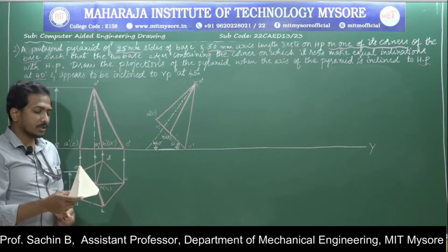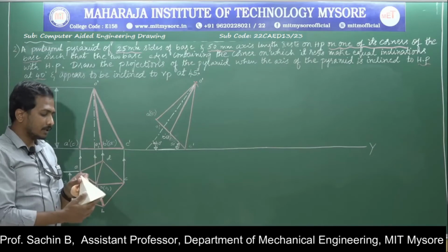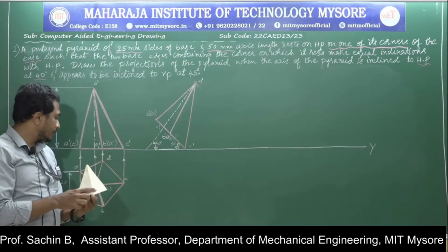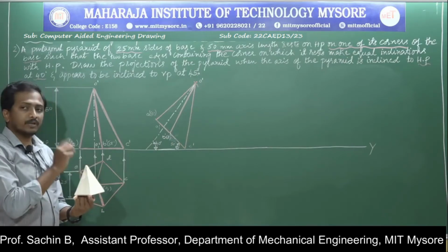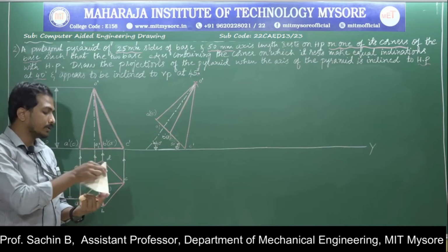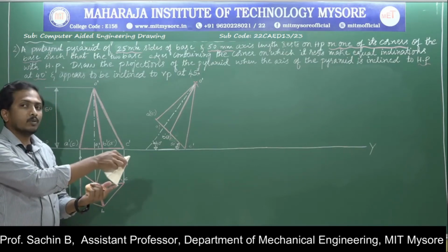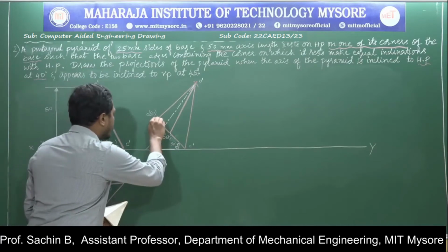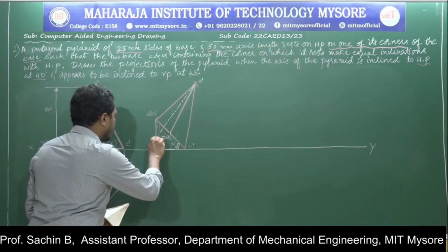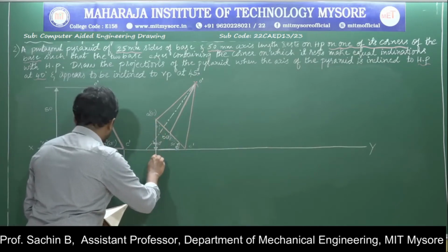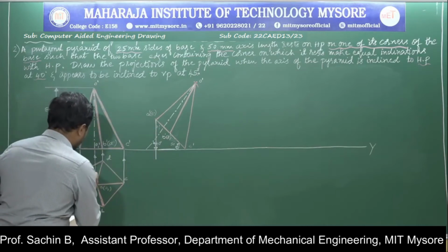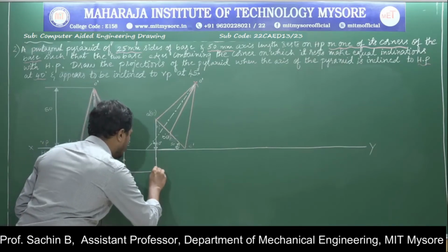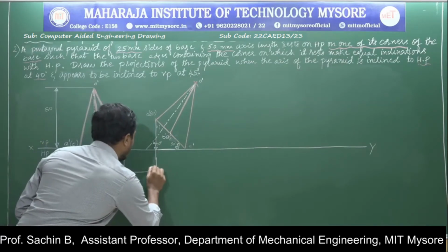Before doing the construction of the problem, we don't have a clear indication of which corner should be rested. After representing the top view and front view in the first position, next I will tilt this, based purely on resting with one of its corners, which I have clearly mentioned here. Now I will draw the projection line to construct the remaining portion. Again I will draw one more projection line from the top view in the first position. This is my E point.